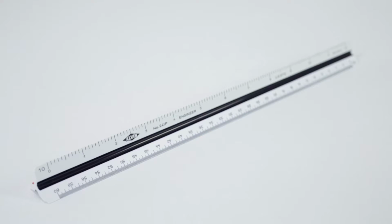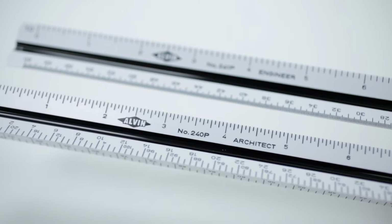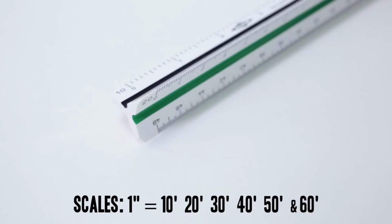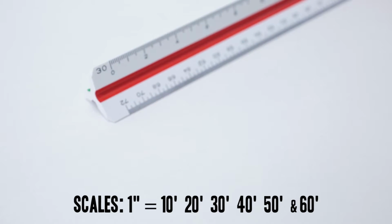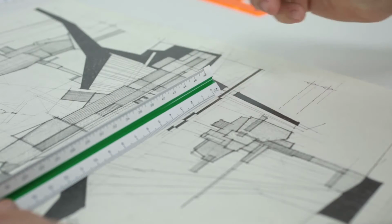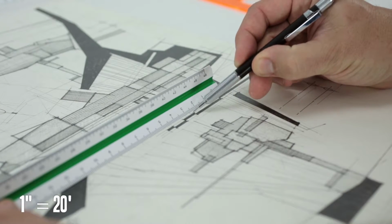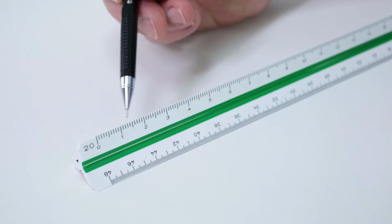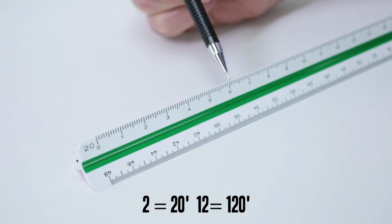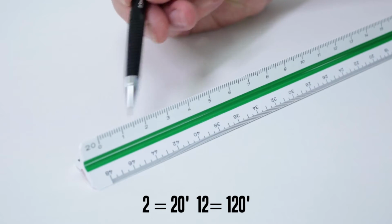The engineer's scale is similar, but represents scale increments of 10. On an engineer's scale, there are only 6 scales, and they're larger. Each number on the ends of the scale represents how many feet to an inch. So on the 1/20th scale, every inch is 20 feet in your drawing. But don't get confused. When you read any number on this scale, you're simply adding a 0, meaning a 2 means 20 feet, or a 12 means 120 feet, etc.